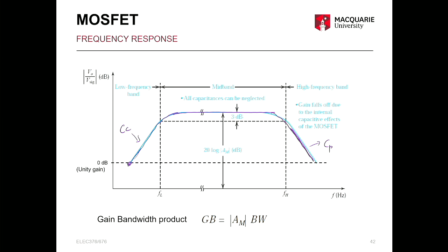Okay, so we talked about 3 dB frequencies. The frequency at which the power becomes half, or the voltage becomes 1/√2, are these 2 points, and the frequencies corresponding to those are FH and FL. The difference between FH and FL is the bandwidth of that particular device.